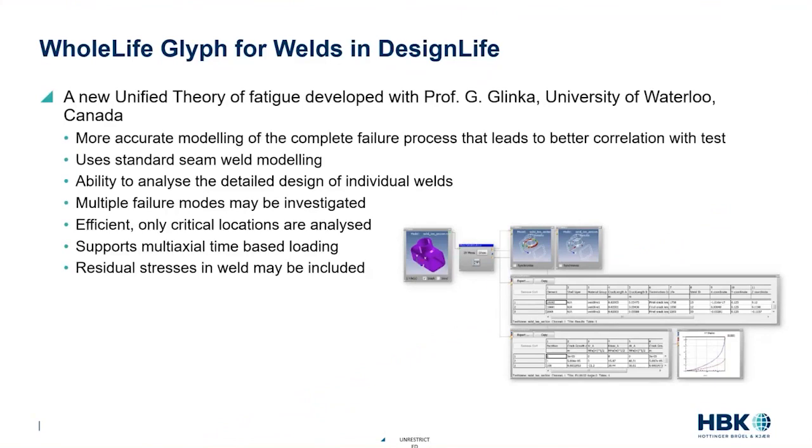The reason we've done this is this gives us a more accurate way to describe the weld fatigue if we know more things about the weld. So again, you don't get anything free. I have to understand more about the weld geometry, stress states, and material properties, but I can go off and do a much more refined calculation. It's using the standard global models we use for Seamweld, either shell or solid. It has the ability to go off and look at individual designs of welds and bring in information such as their stress profiles to describe their behavior exactly.